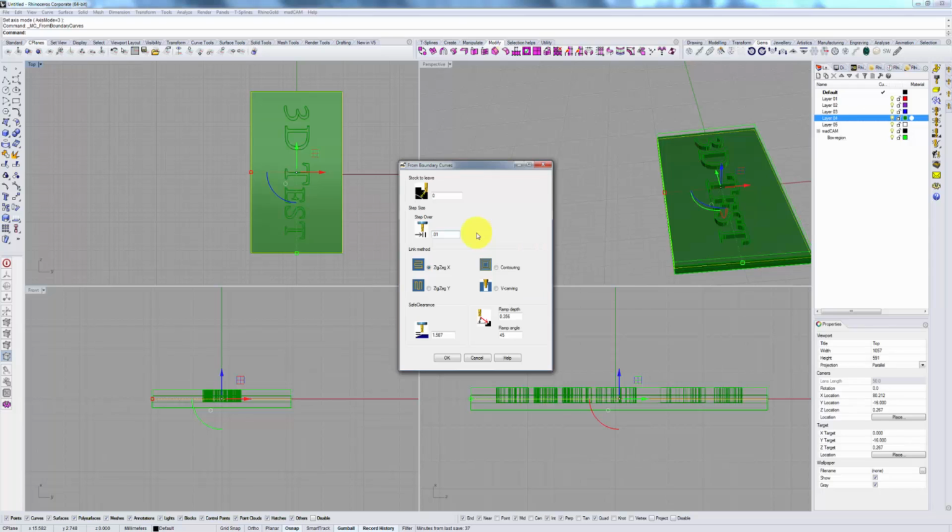In my experience, when casting, you will likely not be able to see less than 0.02 of a millimeter. You will definitely be able to see the step sizes above that, but in some cases that might be okay for flat surfaces, for surfaces that you're trying to polish away and the like. And that decision is up to you.